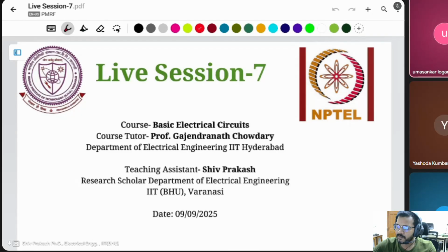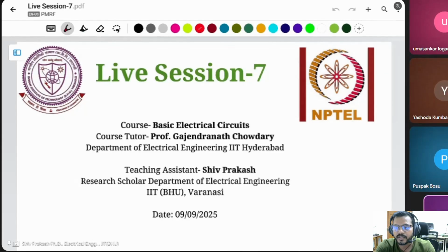Thevenin is applicable for Z-bus formation and fault analysis, and in communication lines. Norton is simply to convert the Thevenin to the Norton. You can't use it directly because there is no current source practically available. You have to make a current source in practice.